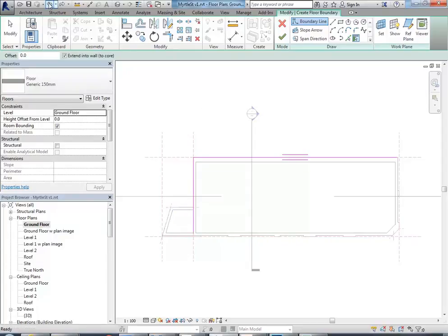The trick I used earlier, just undoing that, was to use tab. So before I click anywhere, you can hover onto the edge of the wall, press tab, and it will chain. Now it's not working as well as it did last time because I've put in the piers and it's not picking up the boundary as well. I'll try it over here and it might do better, but no. Well, it's getting another chain.